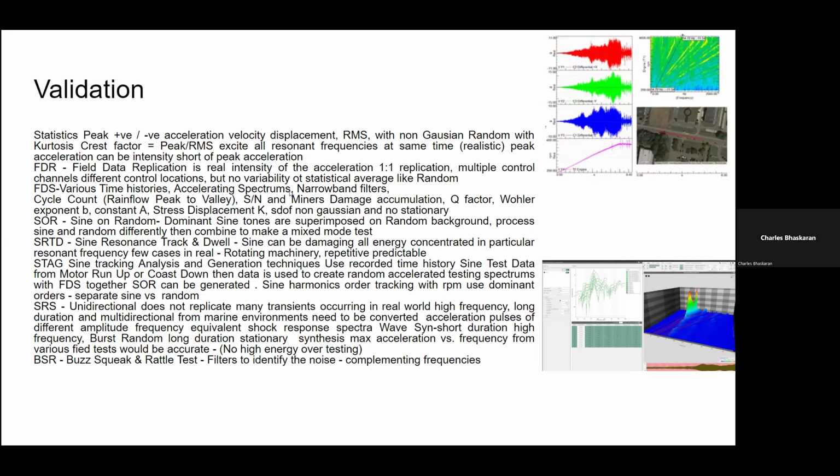What is great about fatigue damage spectrum is that it puts them in their appropriate frequency bins, and we know exactly how many cycles to failure. And then you can use that as an allowable to see, yeah, this curve needs to run 64 hours for validation. Okay, so that is a very common method used today.